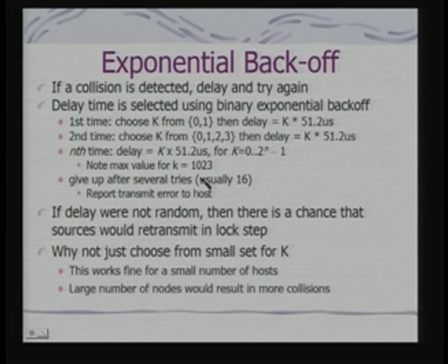Now, what is important to note as an embedded system designer is that because of this random wait parameter getting involved, the performance of Ethernet is not completely predictable. Because if I want to have any real-time service supported on Ethernet, I would like to have predictable performance. Because of this exponential backoff with a random selection of delay, the performance of Ethernet is not strictly predictable.